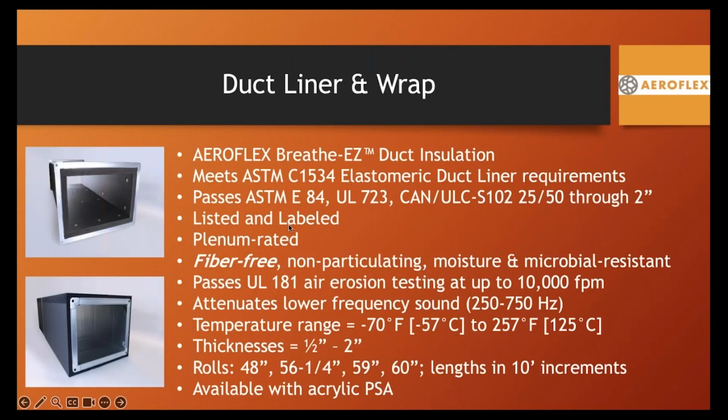So what can we offer? How can we help with a product solution? AEROFLEX Breathe-EZ is a closed cell elastomeric duct insulation for liner or wrap. It does meet the ASTM requirements for an elastomeric duct liner. It passes the 25/50 flame and smoke indexes through 2 inches thick, is listed and labeled, and it can also be called plenum rated.